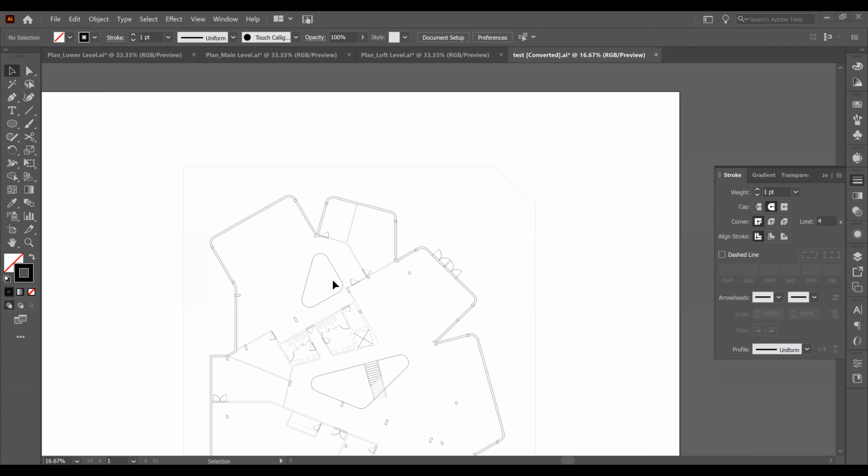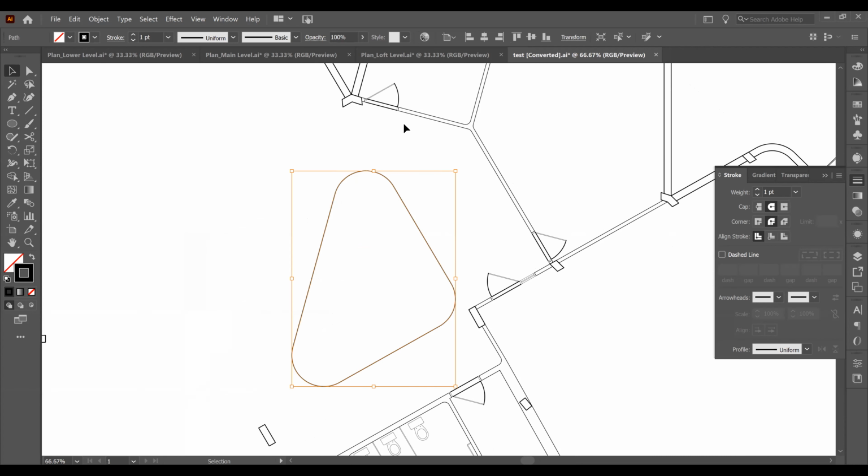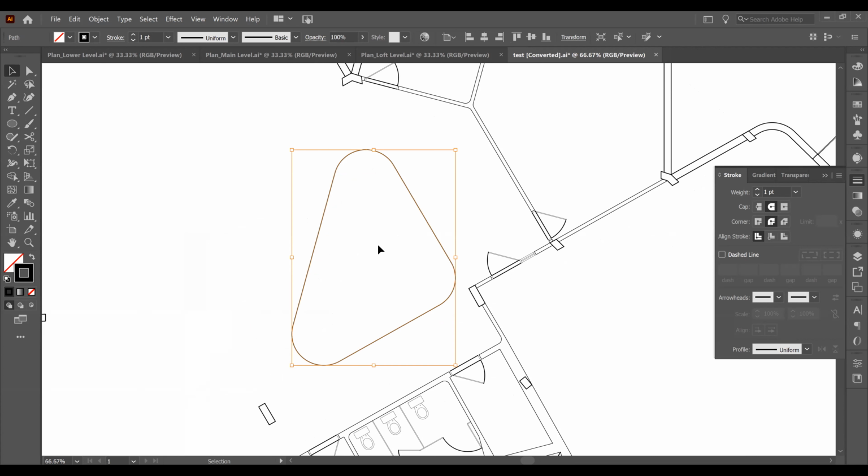Oh, okay, Lily. So Lily asked about making hidden lines read as continuous. This is an example of an above line here that I've joined in Rhino. So I'm going to make it a dashed line. And here you have all the options for how the dashed line gets expressed. You want to make sure that this is selected, aligns dashes to corners.